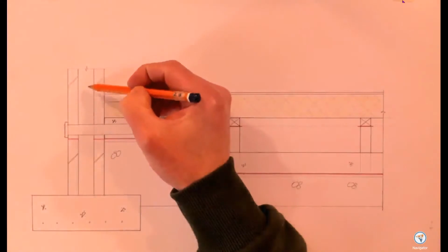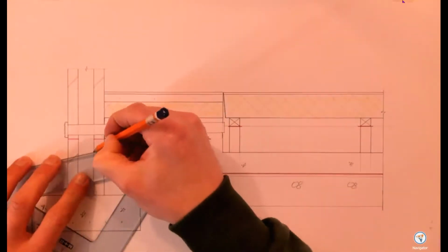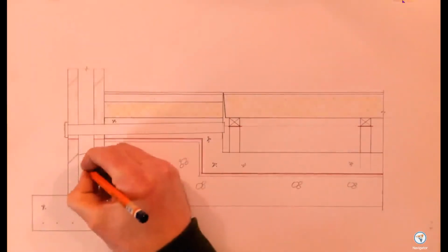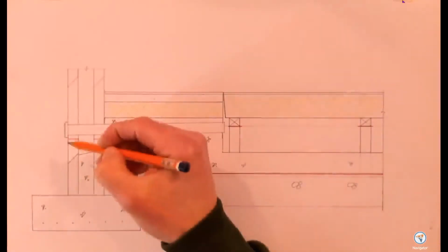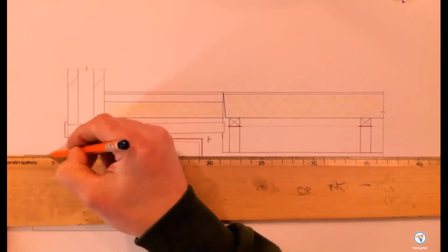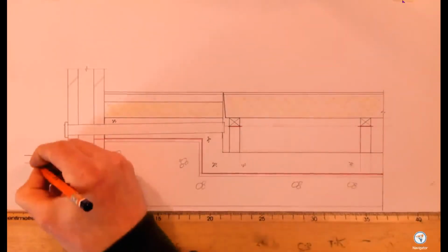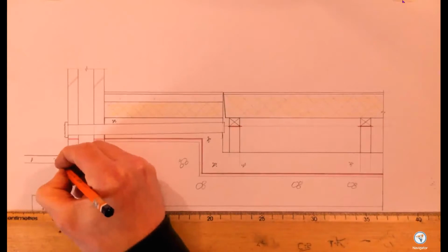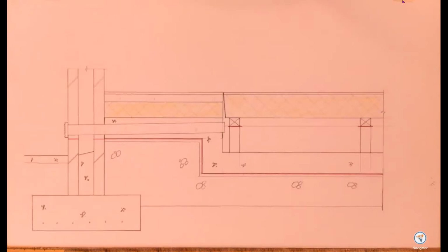I need to show my insulation here as well, and I need to show my outside floor level. Below the damp-proof course, so it has to be below the damp-proof course, I'm going to put in my concrete fill. So in other words, the rising walls, to stop them collapsing, need to have concrete filled in. Minimum 150 millimeters below floor level is where our ground level is. So down here is my outside ground level, and I can put that in anywhere, and I can put in maybe a concrete footpath just to show it outside. But again, it has to be a minimum 150 millimeters below the damp proof course, and again the vent has to be above that also.